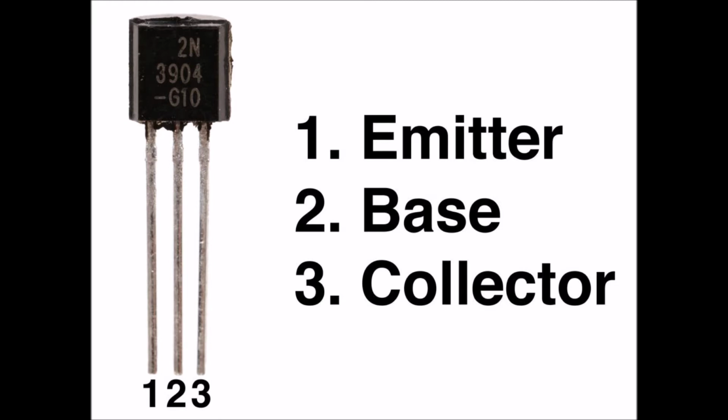The exact DC voltage at the emitter depends on the resistance of R1 and on the bias at the base. We set the DC base bias by adjusting the ratio of the values of resistors R2 and R3. The DC base bias can range from 0 volts or ground potential to plus 12 volts, which equals the power supply voltage. Normally it's a couple of volts.